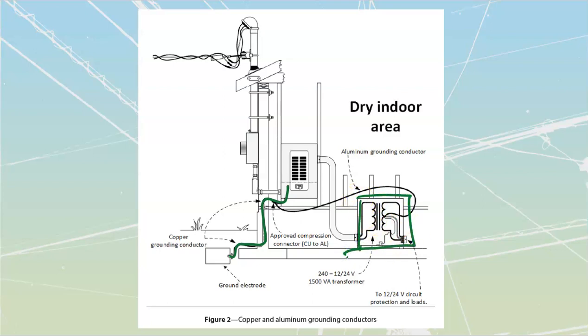These are going to be defined as being separately derived systems inside of my Canadian Electrical Code, where I'm taking my voltage over here. I got a 120/240, and I'm going to feed 240 in onto one side of my transformer, and then out the other side, I'm dropping that thing down to 120, down to 12/24. Maybe there's a bunch of low voltage lighting, whatever is inside of here, it doesn't really matter. We run that out of that transformer to its circuit protection, etc.